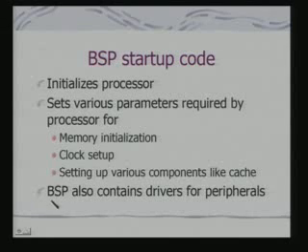So the BSP or board support package forms a very important component for all operating systems which are targeted for embedded appliances. And for each appliance or target card, you may need to configure your board support package for a particular OS. So for example, if I am talking about eCos, eCos is an OS targeted for embedded appliances. But for a particular card, I need to properly set the board support package so that on that card or target system, eCos can operate properly.